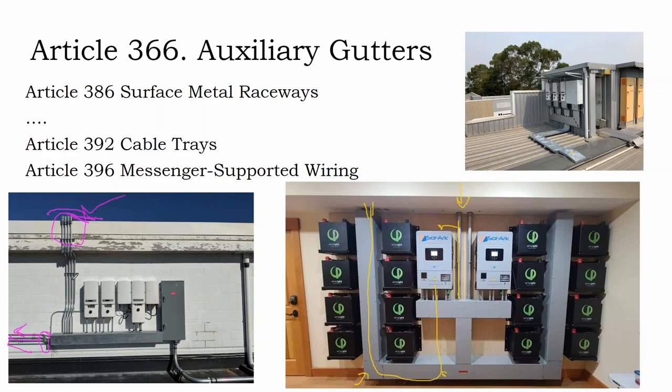And each one of these sections has to be bent and made up and attached and drilled and knocked out, and then the fish cable put through for your conduit pull, and then that taped off and tied to all the conductors that have to be prepped individually when you're pulling them, so you can pull them all at once.